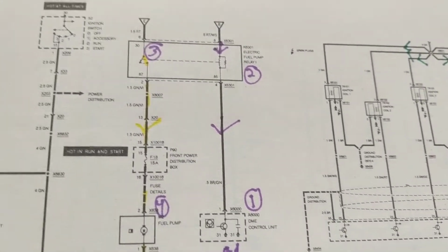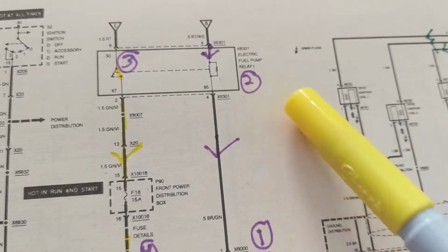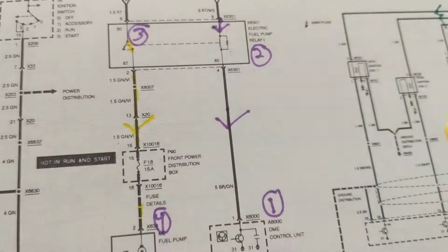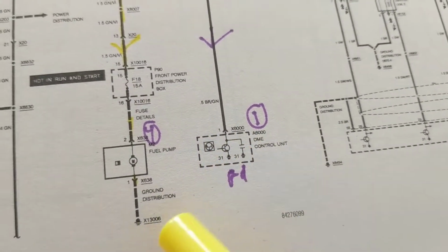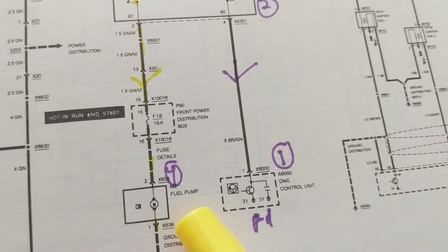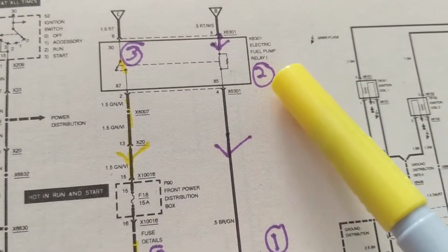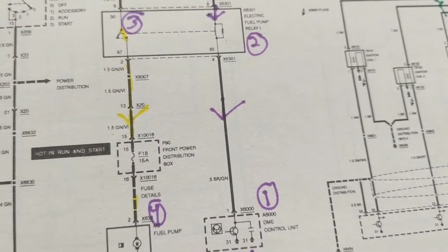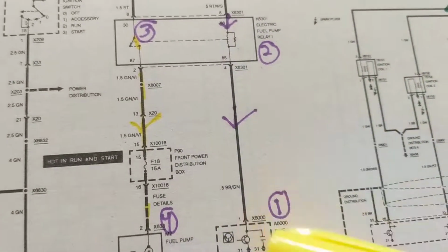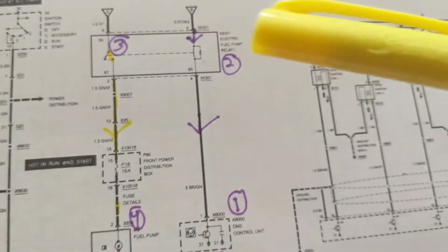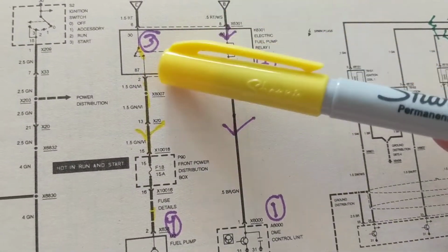So as we said before, let's say we're concentrating on this. We know this is the symbol for a relay. We know this is the symbol of a transistor. And we know this is a symbol for a fuel pump and the fuse. Electrically, an electric fuel pump. Now, before troubleshooting, we have to understand how it works in the first place, obviously. So what you're paying attention to, again, is key components, main components.